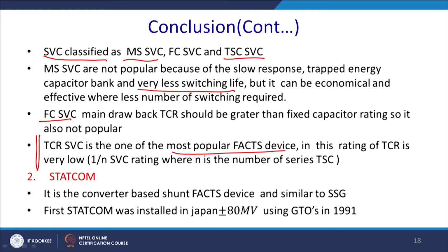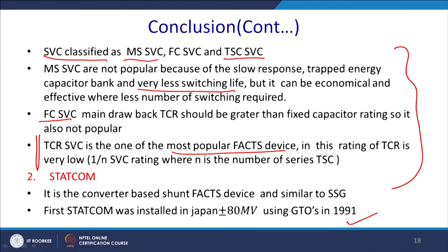And about all this shunt compensation, this is basically a passive kind of device. It essentially injects a passive component, a capacitor or variable capacitor, but we can have a solution with the STATCOM, where it generates this reactive power and current by manipulating the angle between the voltage and current, and this STATCOM is definitely more preferred. So, there are FACTS.